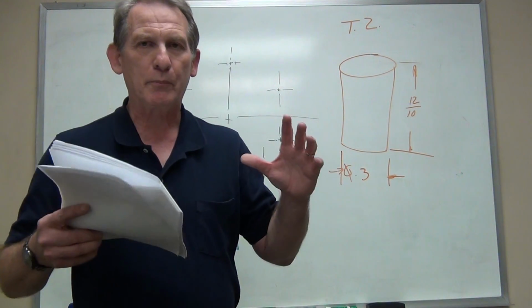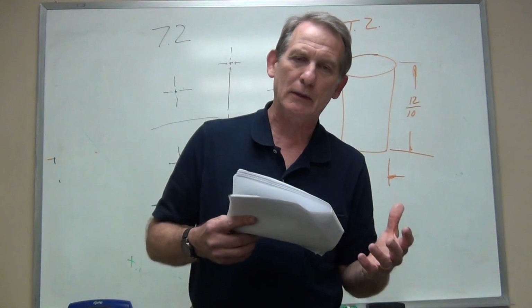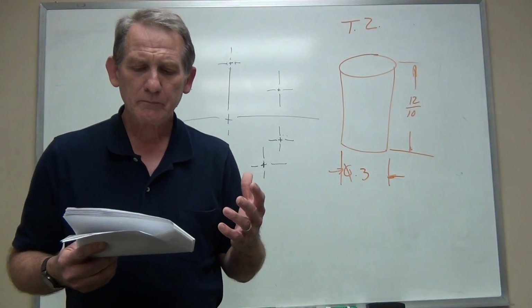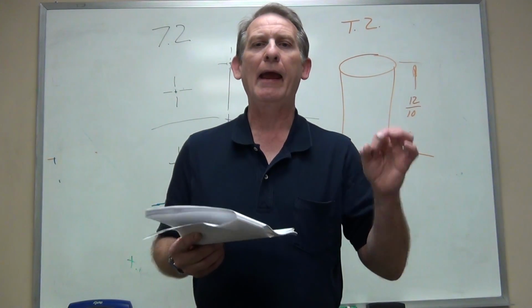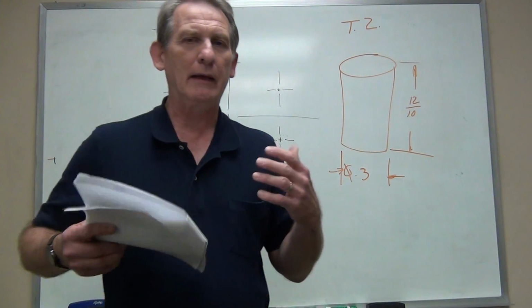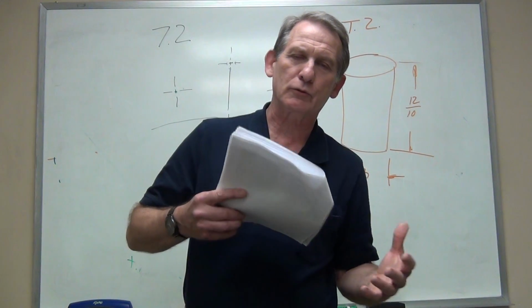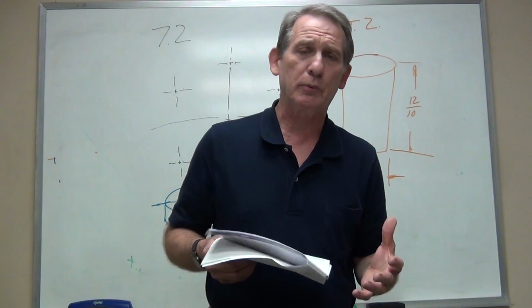And then once we have that perfect geometry established with the basic dimensions, we can use those locations to hang a tolerance zone. And a tolerance zone obviously can be as big or small or round or square or whatever we want to do. That's the idea of GD&T, that we have complete control of it.